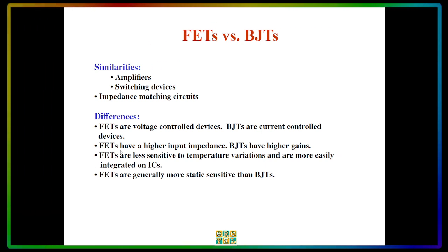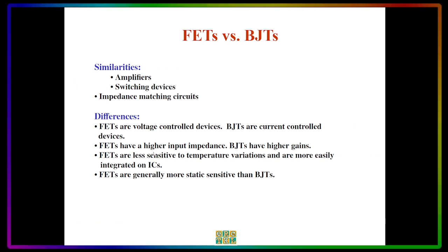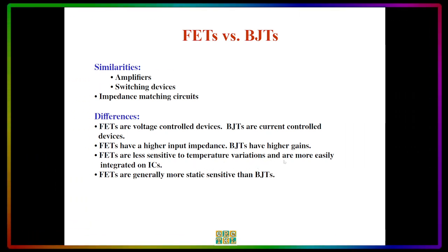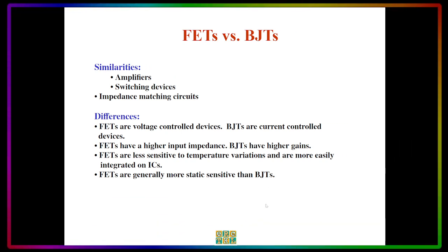The FETs have a higher input impedance, and compared with BJT, they have higher gains. FETs are less sensitive to temperature variations and are more easily integrated on ICs. FETs are generally more static sensitive than BJTs.